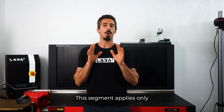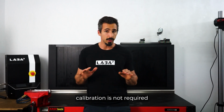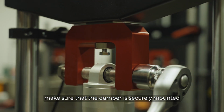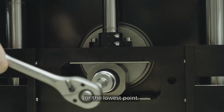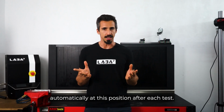This segment applies only to Scotch-Yoke shock dynos. If you have an EMA dyno, calibration is not required and you can skip directly to the next section. Before running any tests, make sure the damper is securely mounted and the dyno mast is at 6 o'clock position, or the lowest.